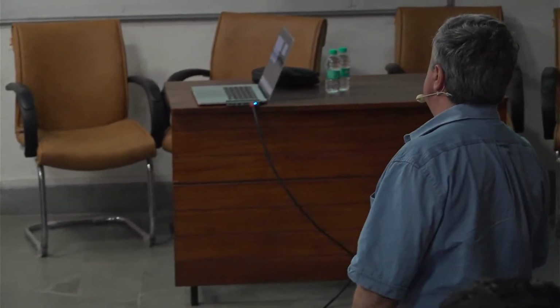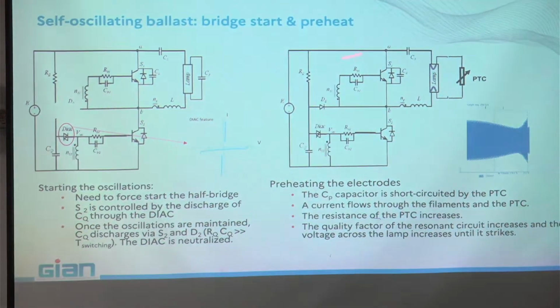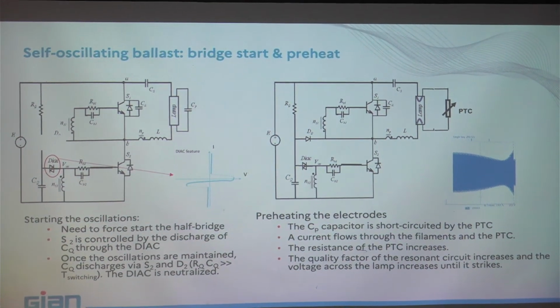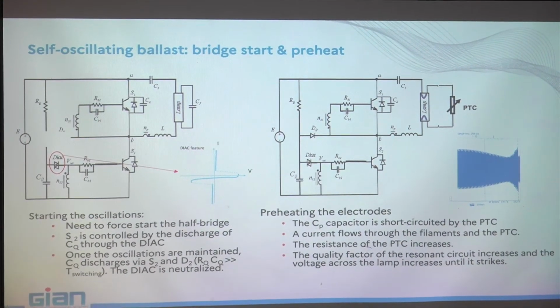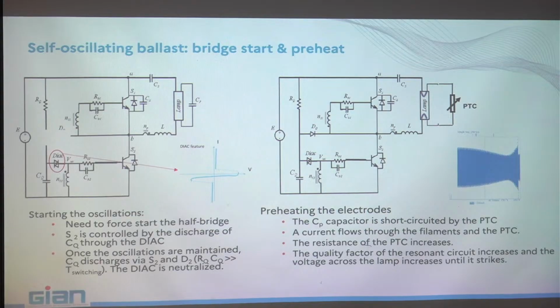The way to avoid this rapid evaporation is to preheat the electrodes before the breakdown. And high-end ballasts, electronic ballasts or drivers, can do it. They can preheat the electrodes in order to reach the right temperature at the moment that the pulse for igniting the lamp is sent to the lamp, and this can reduce the problems that are harming the lifespan of the lamp.